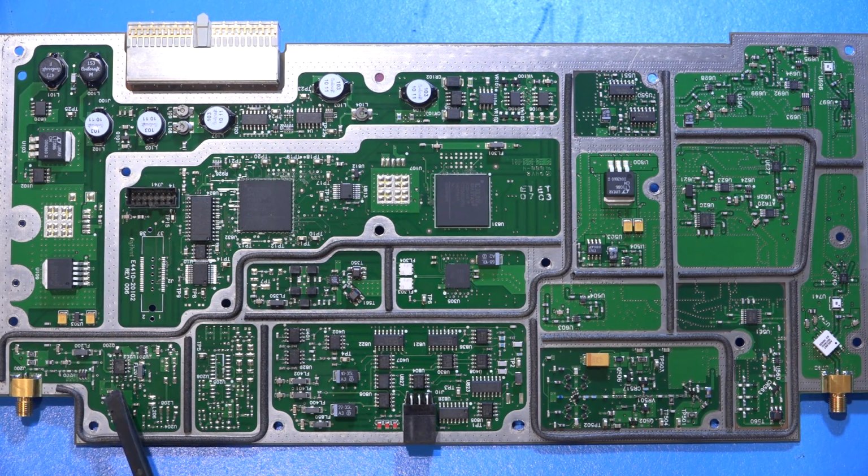So the reference has to get divided down. You don't want to work with a 4.8 gigahertz reference in a PLL. So there's some programmable divider, and that's most likely what that mystery chip is. So I actually looked into it, and I'm going to show you what I think it is and how it looks like on the inside. But you won't be able to find a data sheet of it because it's a part designed for Keysight by ON Semiconductor. So that's the input reference handling.